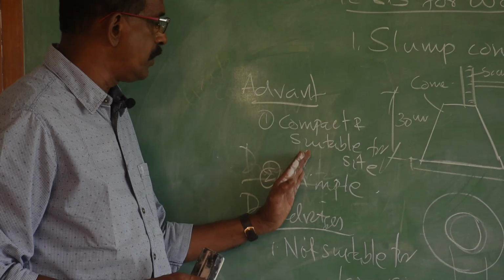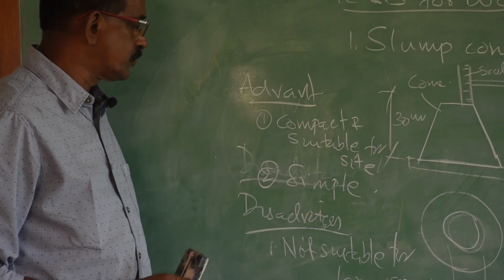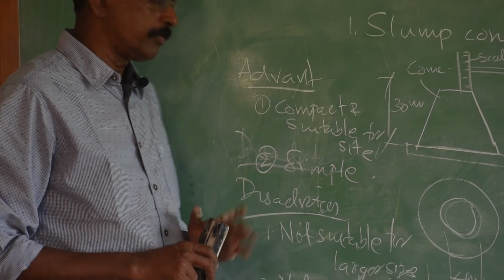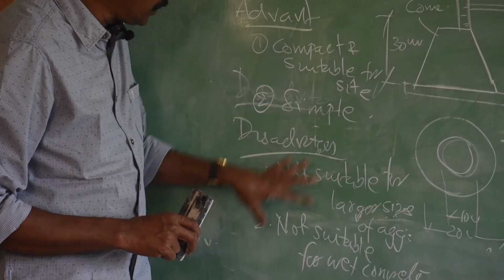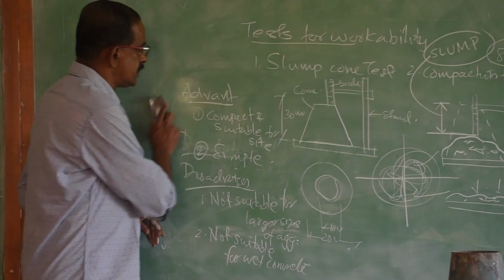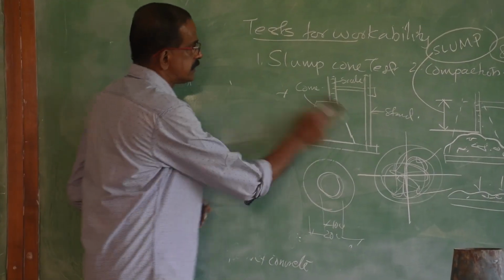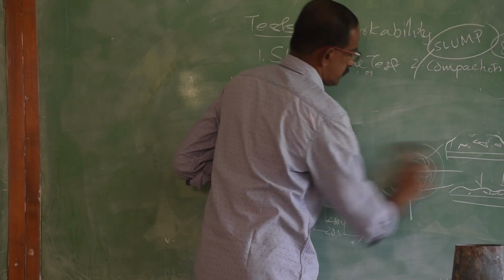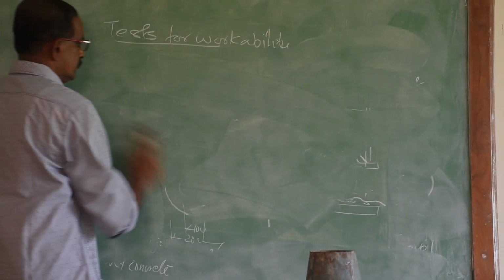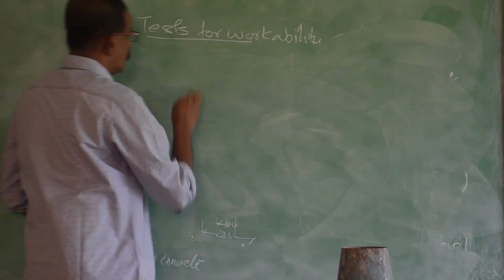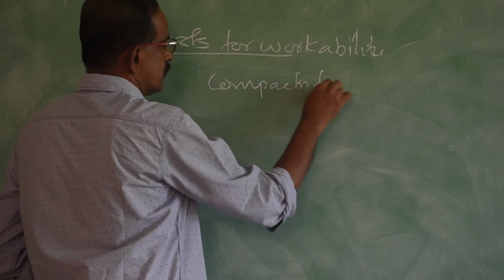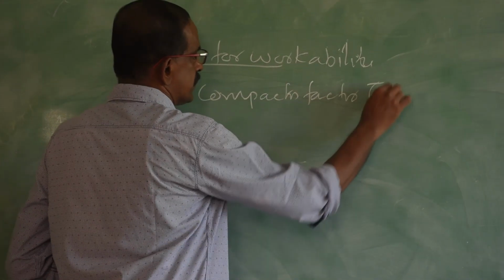Advantages: it is simple, compact, suitable for site use. Disadvantages: not suitable for large size aggregate, not suitable for wet concrete. To overcome these two disadvantages, there comes the second test, that is the compaction factor test.